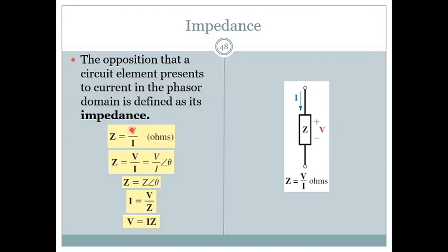So this representation is in the complex domain, and this is in the complex domain, and therefore we will have to define another parameter, which is the impedance. It is not just the amplitude that matters, it is an amplitude and an angle. So V angle theta 1, I angle theta 2. So V over I, angle theta 1 minus theta 2, becomes theta.